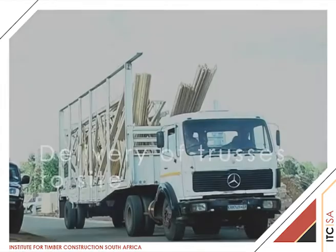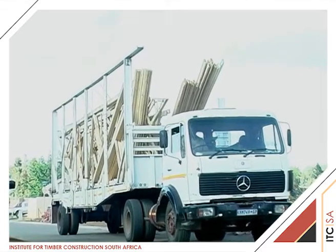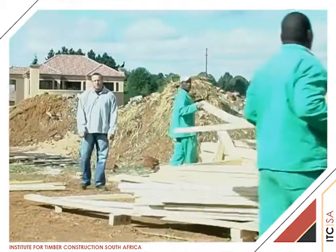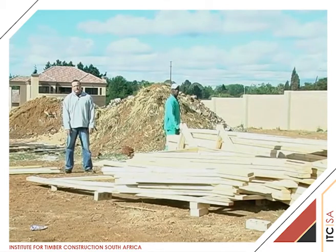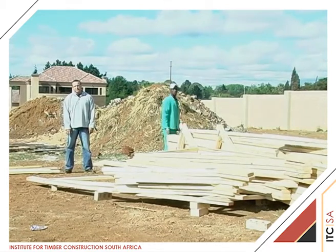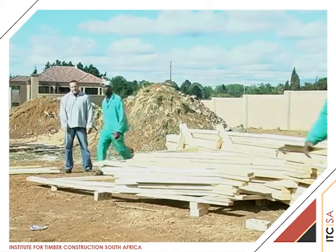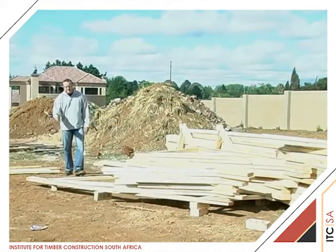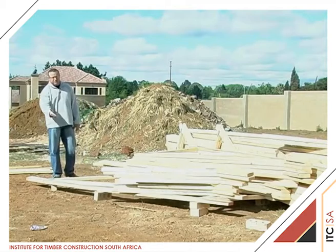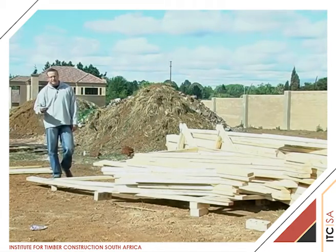The truck has just arrived with the pre-manufactured nail-plated timber trusses. What is very important to note is that the site is prepared for the delivery and stacking of these trusses prior to them being erected onto the roof. And that is that the surface where they are going to be stacked is leveled out. And as we can see, they are elevated away from the surface level to protect them from any damp.